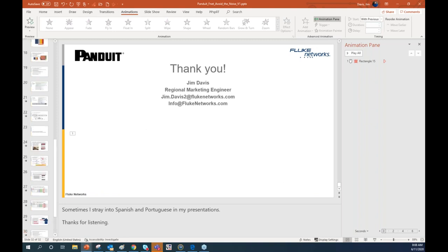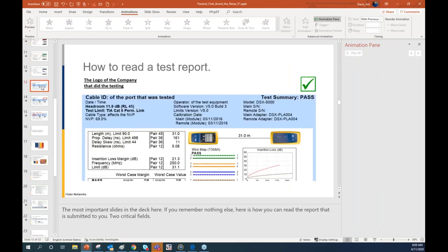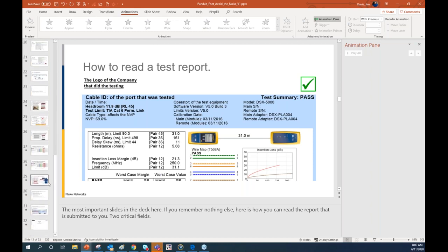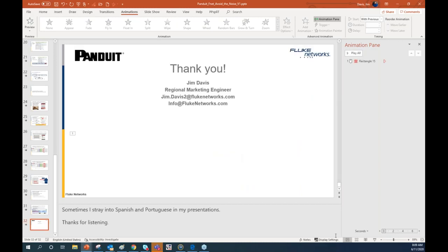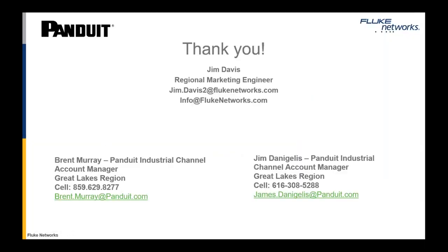And from there, you could actually look at some of the other areas of the standard in terms of things like bend radius control. Are they controlling distances? Key elements of the TIA standards that you could look and see, are they doing these things? That takes a little more expertise and a walkthrough to be able to do it. So the test report is really the key primary thing.